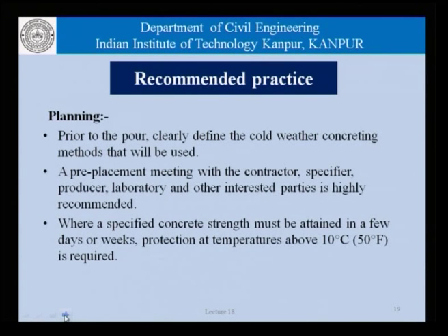So basically what this 10 degrees says is that during the curing period, the immediate neighborhood of concrete must be maintained at a temperature of about 10 degrees centigrade. That obviously requires heating of the environment. Now, how we achieve it is a different matter.